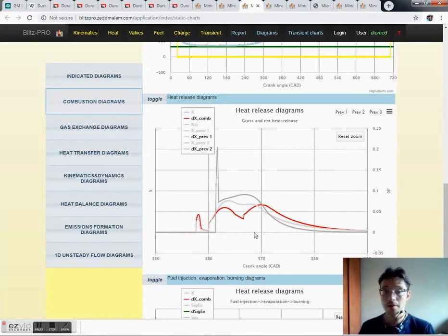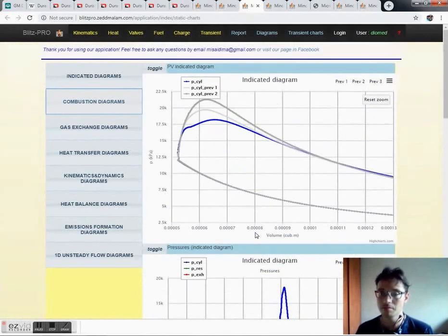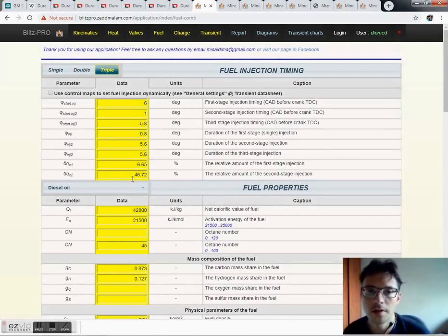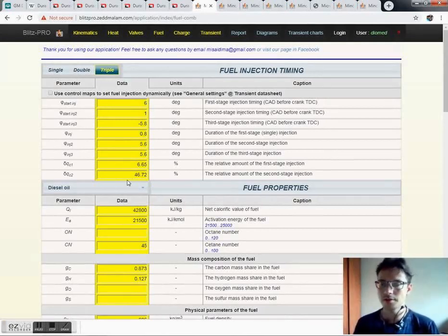And it's obvious that we made some brief calculation, but actually we can play with these numbers and choose different shares for the pilot, first main injection and post injection, or third main injection, and we can adjust the fuel injection to the combustion process, to get the desired combination of maximum pressure and maximum pressure rise rate, and of course the fuel consumption.